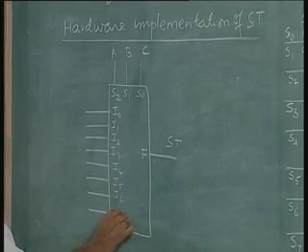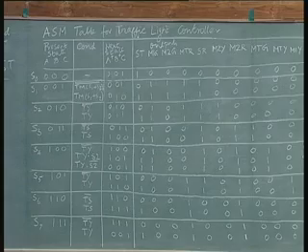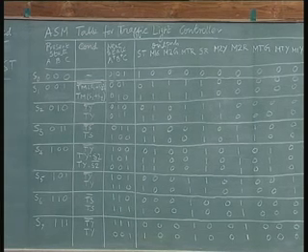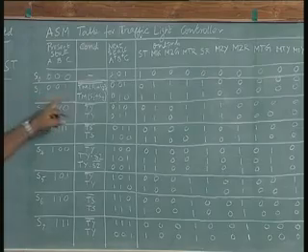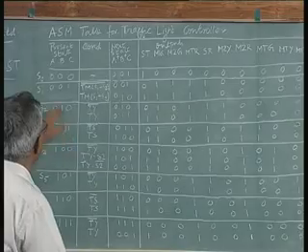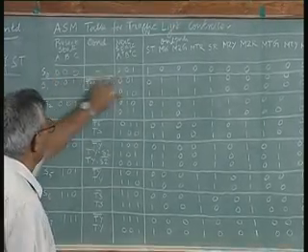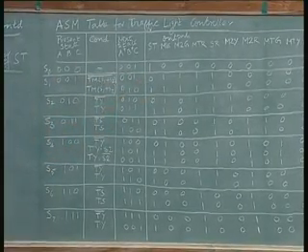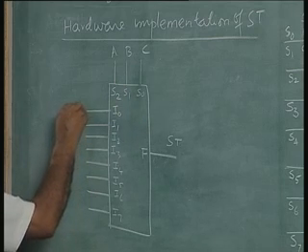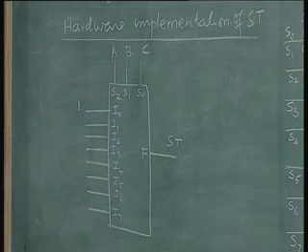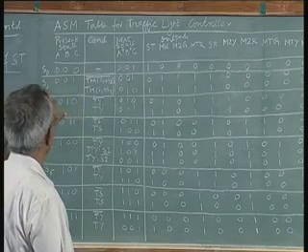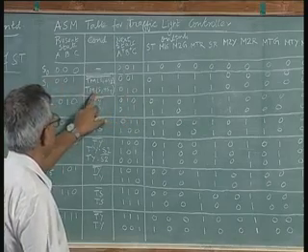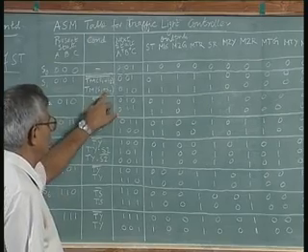There are 8 inputs, I0, I1, I2, I3, I4, I5, I6, I7. What are the conditions under which the start signal is 1? That is all we have to map in this multiplexer. Start is 1 for the present state 0 0 0, so if we are in present state 0 0 0, start is 1. Start is 1 in S1 provided the condition Tm S1 or S2 is valid.